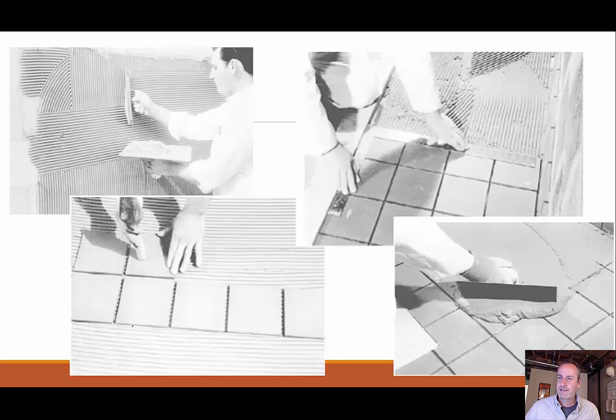Here we see the tile installation. The first step is to apply this whole layer of your mortar. So you can see he's applying this mortar. The reason we have these ridges here is when we put our tile against that mortar, it basically allows it to push the air voids out and create a very good suction, right?